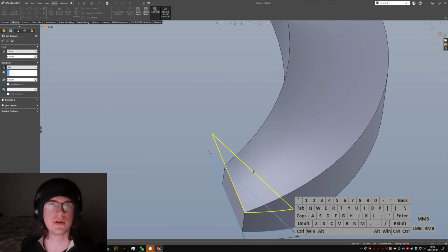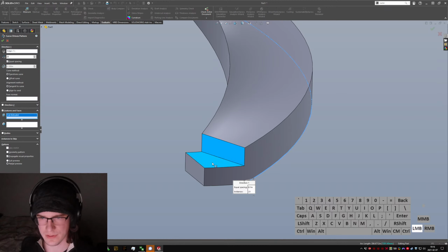Yeah. Let's just do something a little bit silly. Let's try a curve-driven pattern. Direction 1, this guy. And that should bring us way up to the top. Oh, it might actually be a little short. Well, let's find out. Let's just try it. Features, this guy. Tangent to curve. Base normal. 15? Whoa, that works good.